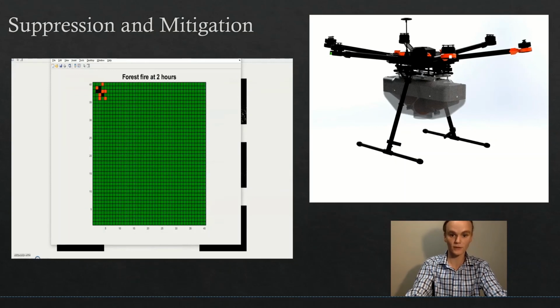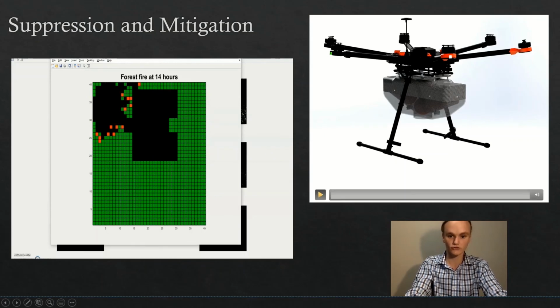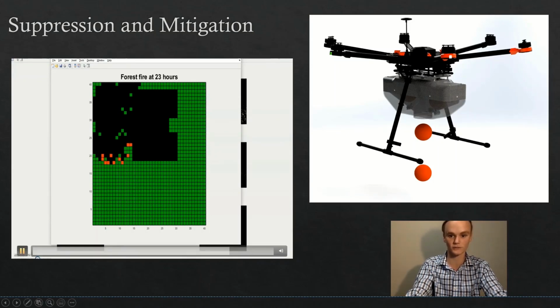The firebreak function is designed to intersect fire paths going into sensitive locations. Deviation from the path will initiate guidance from the mother drone to the swarm to direct the burn line back into the prescribed area, as shown by the simulation. The suppression drones dropped 0.4 kilogram Elide fire suppression balls onto open flames to suddenly remove the oxygen feed to the fire by covering the area with monoammonium phosphate, a typical fire extinguishing material.